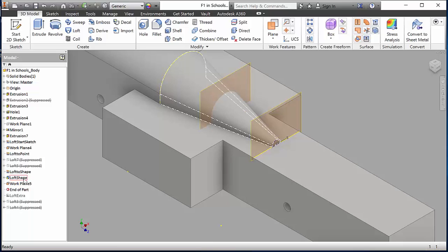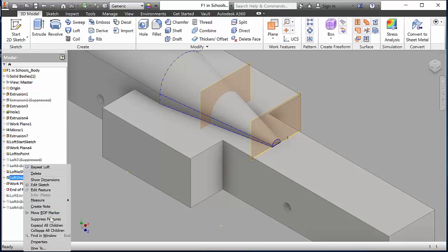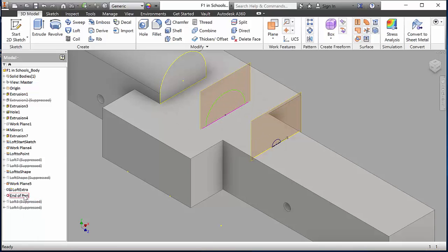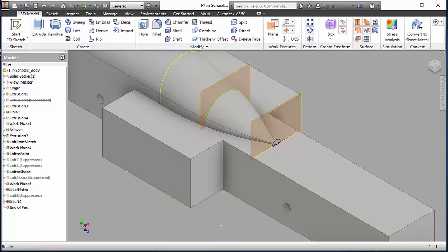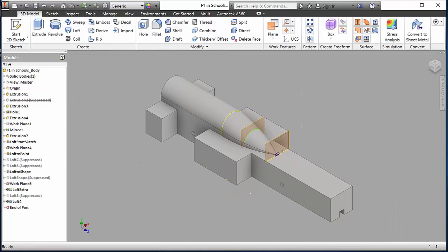I've created another work plane approximately halfway between the front end and the back end. I'm going to suppress that feature I just showed you, add another sketch, and this time there are 3 selections that I created. And you can see those 3 sketches right there. Unsuppress the feature, and that gives you a way to control the shape a little bit better.